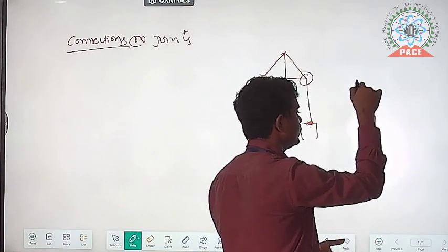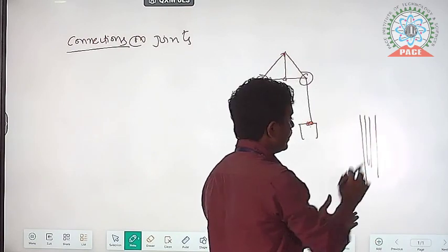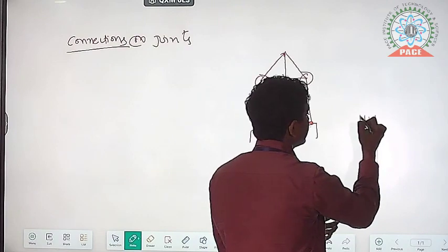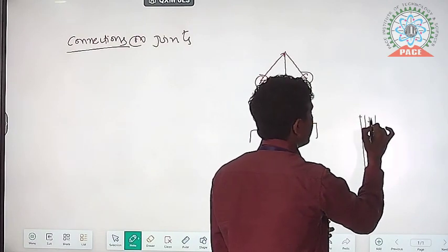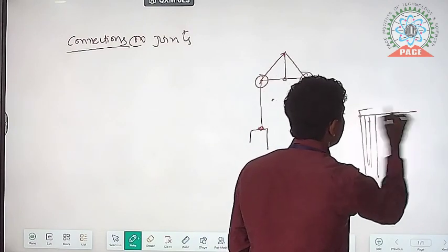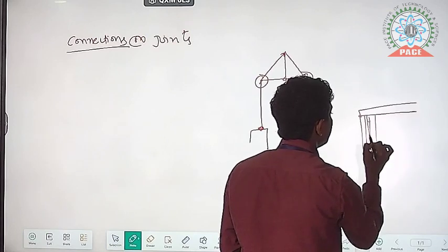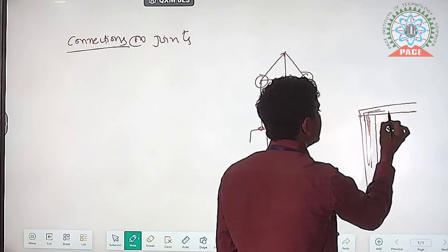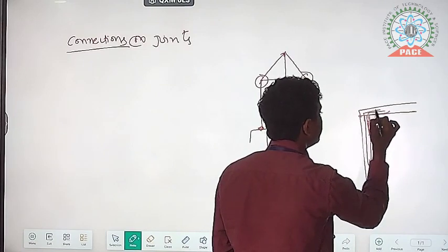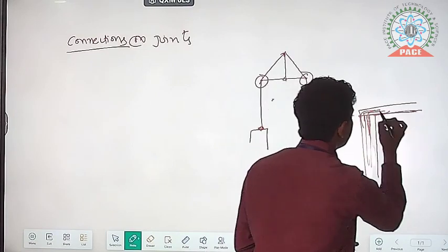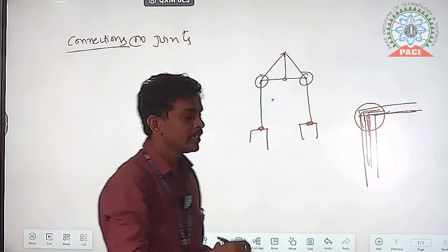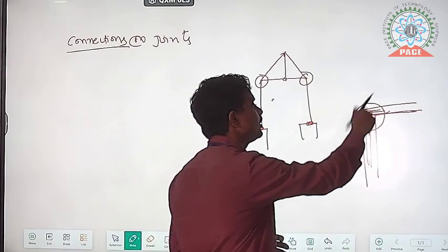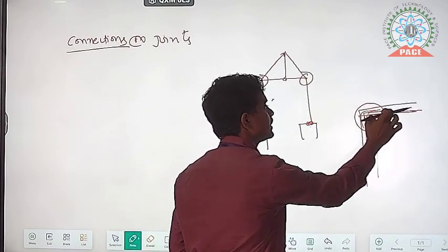And then if you do the slab, this reinforcement will go to the top and then come to this side, and likewise the slab reinforcement will also come to this side. So this is the joint part. Reinforcement will continue and enter into the slab. Sometimes this reinforcement will go up if any stair is also there. That is the joint.